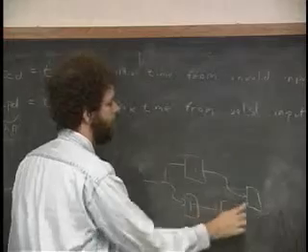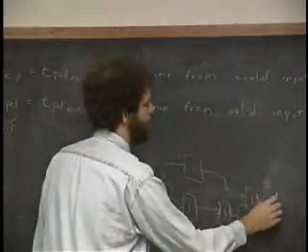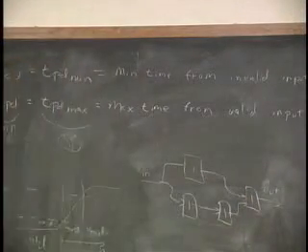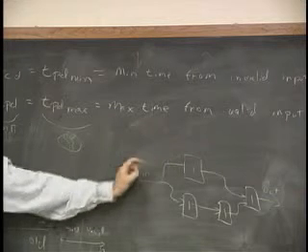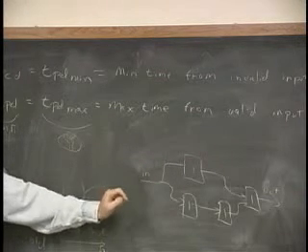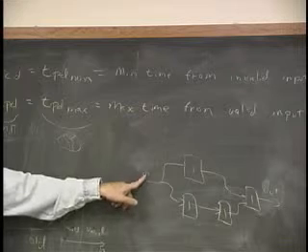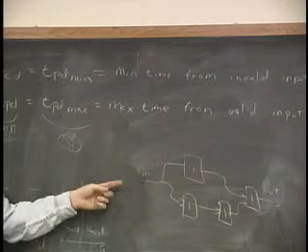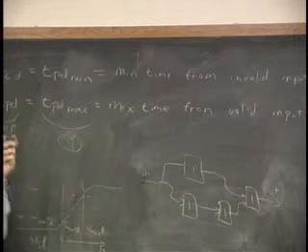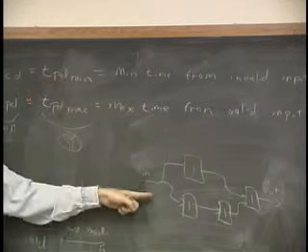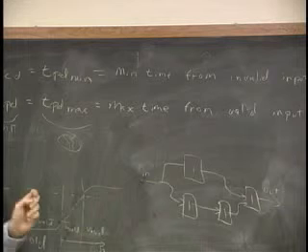Let's say I had a circuit that was made up of units whose time delay was all 1. Oh, I'm sorry. Let's say I had a circuit which had two paths through it, one of which had a time delay of 1 and the other which had a time delay of 2. How long does it take for a contamination or any kind of value here to go from in to out? Well, the minimum time it takes is 1, 2. The maximum time it takes is 1, 2, 3. So that would kind of indicate that TPD min for a circuit like this is 2, and TPD max is 3. Which is absolutely true.